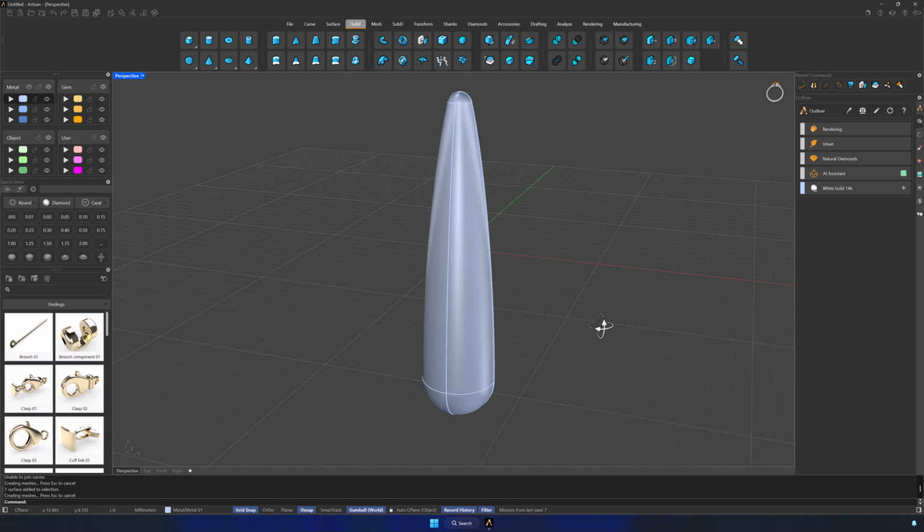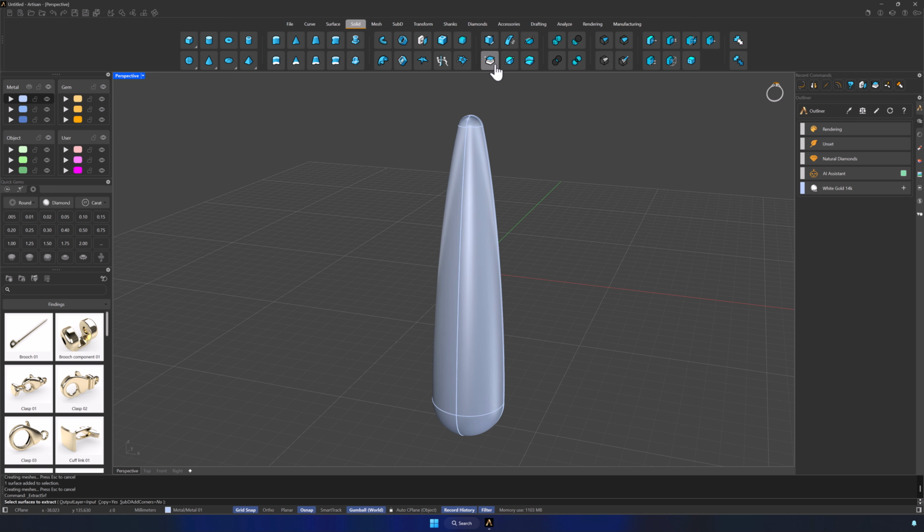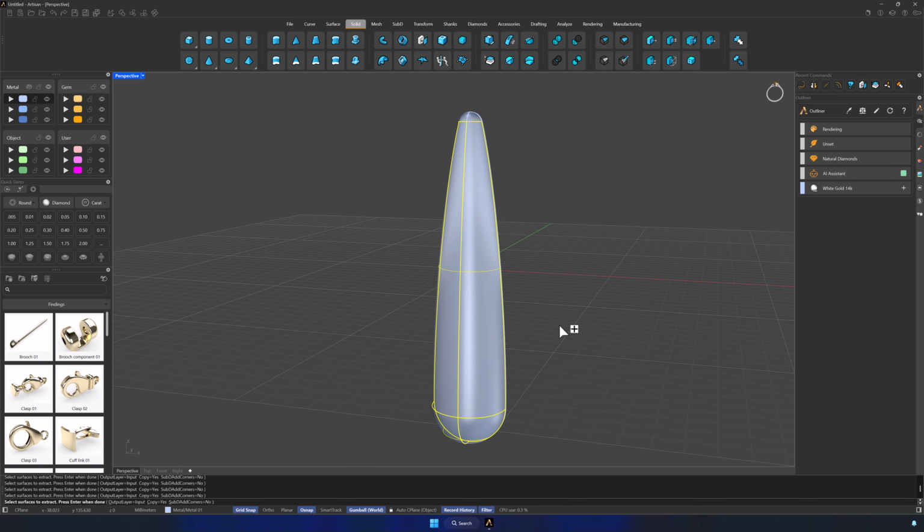I will use Extract Surface to take the outer surface of the solid. In the command bar, I will change the copy option to Yes, so we create another surface. Then I will select the 4 lower parts of the model. Without deselecting, click Join to create a single surface and optionally move it to another layer for better control and visualization.